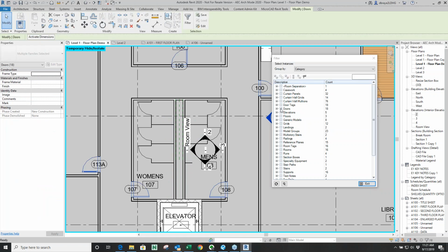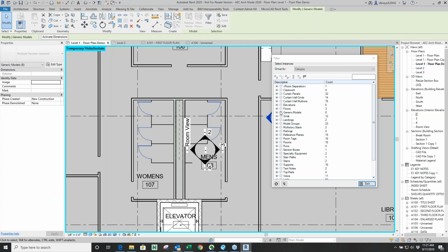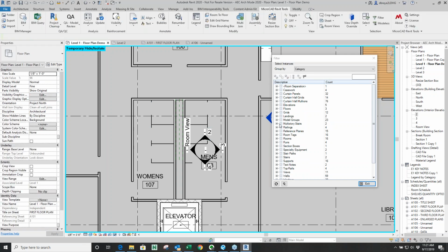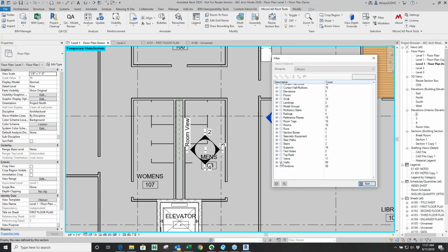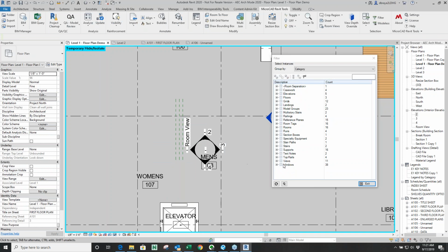I can say, hey, pick all doors, HH on the keyboard, and it just disappears all those. So as you're working and selecting certain elements, let's say if I do generic model, I can select any category down here, allow me to select those elements, and it will disappear off the list. So let's say I did not doors, but walls, and I did HH. As soon as I did HH, you can see it just removed from the list here.